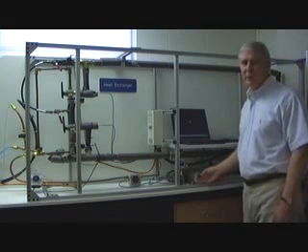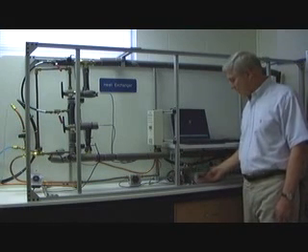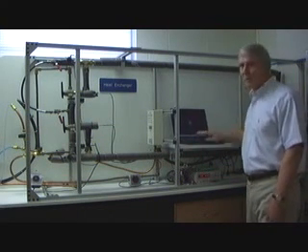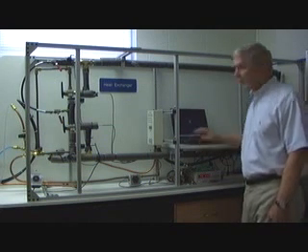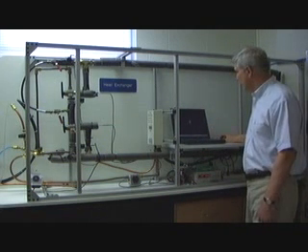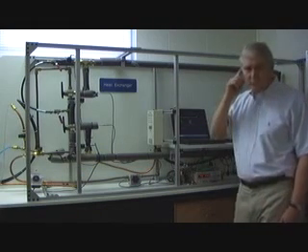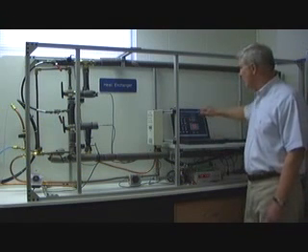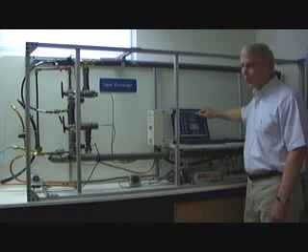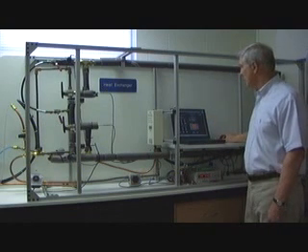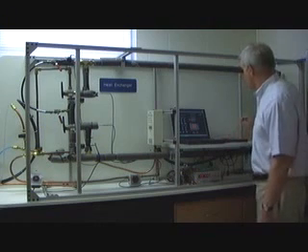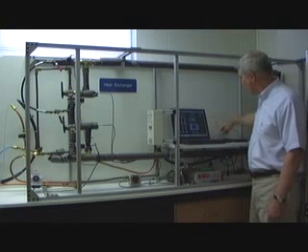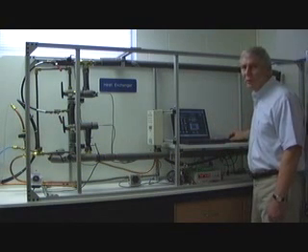To operate the equipment, first turn on the power supply and ensure 24 volts. Then turn on the computer. The computer's already on for this demonstration. Click on the icon in the center of the screen, the LabVIEW icon, and wait for it to come up. When it comes up, you're going to select the appropriate configuration, meaning either the flow type, parallel flow or counterflow. Once you have that selected, click the Run button. Disconnect the computer from the line power by disconnecting this line here from this external battery in order to reduce noise in the system.